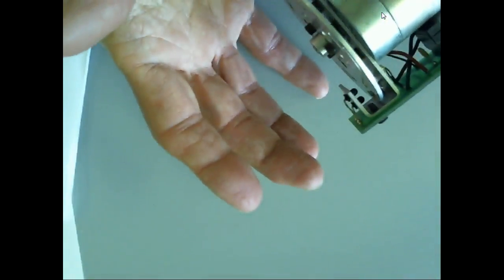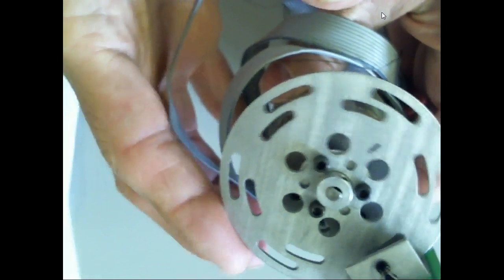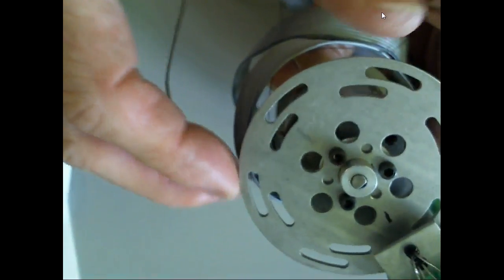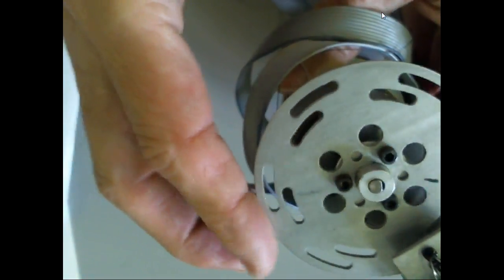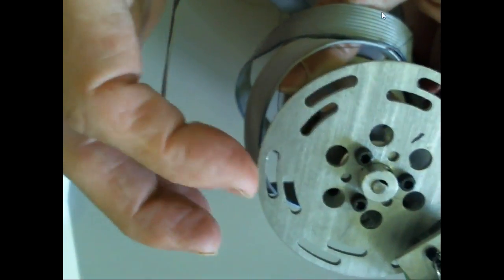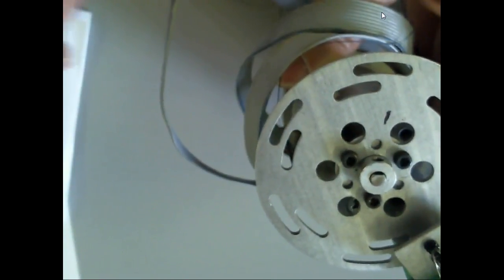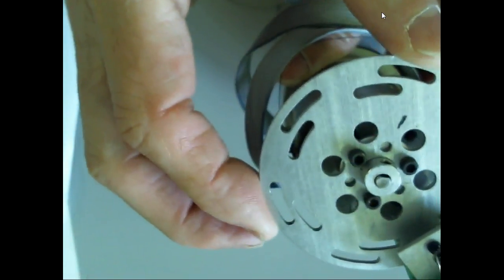So it's got infrared diodes on one side that transmit light, and it's got photodiodes on the other side that detect light. So when this thing spins, you'll notice when I spin it in one direction, this outside band would give me the pulse first. You see what I'm talking about? And then when I spin it this direction, the inside band would give me the pulse first. So depending on which one occurs first, that gives me an indication of what direction.